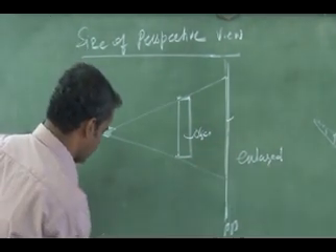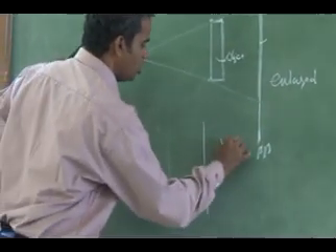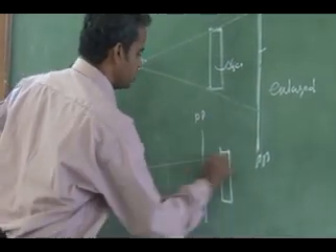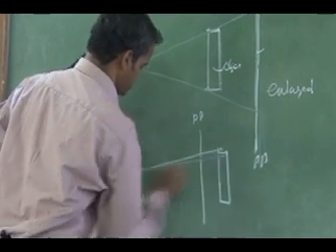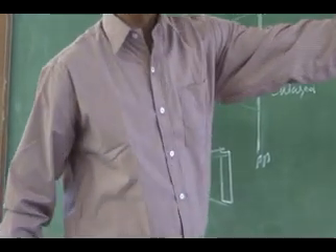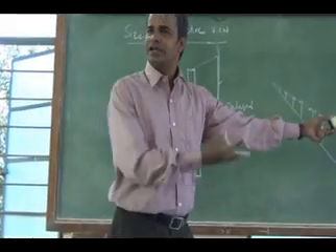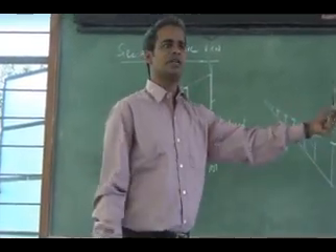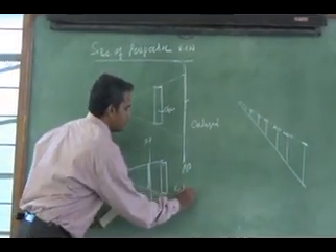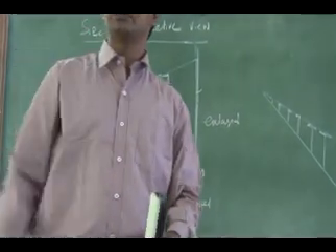The same thing, if I have the object behind the picture plane, what will happen to my perspective view? It is reduced. So it is a similar condition to what we drew previously in the layout. So that is a reduced perspective I have to obtain, because the picture plane is in front of the object. So I will have a reduced size perspective. When will I have the same size of the perspective?